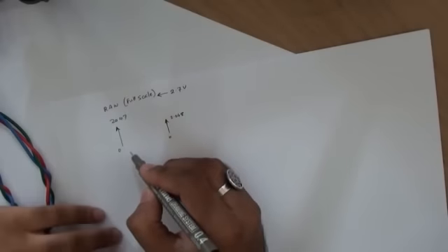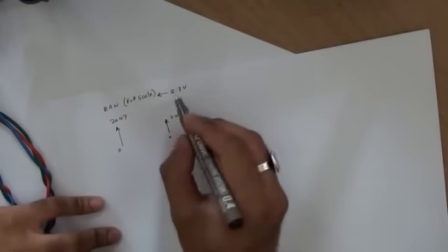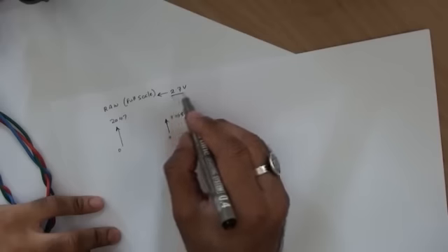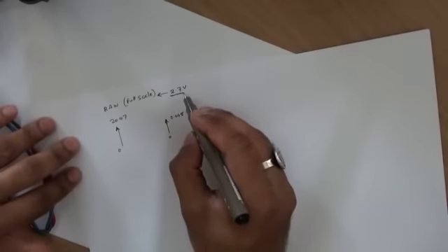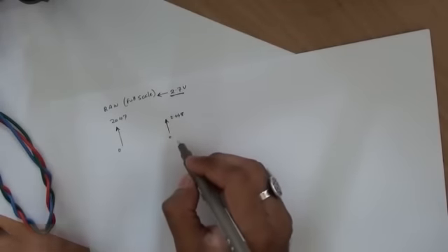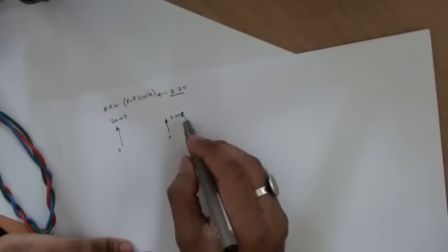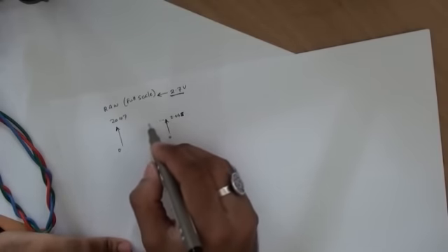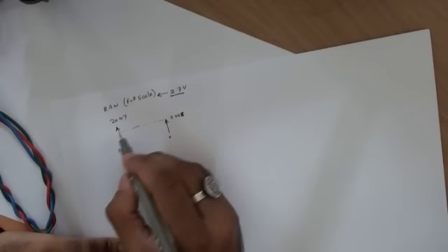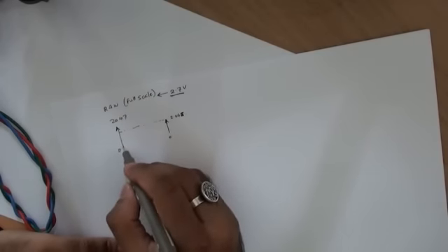So you can use this to come up with a measurement for your motor volts, which we assumed at the beginning is somewhere around 2.7 volts, but of course it doesn't have to be. What is really constant is the actual 2.048 volts that you get out of the voltage reference, which will correspond to a given raw value when you're measuring with the inbuilt ADC.